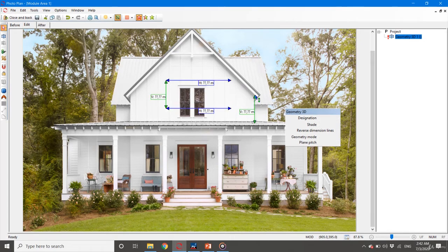Blue is the same, except for the horizontal lines with the capital letter H. Remember always to enter the correct distances or measurements so you can get accurate results and conclusions. I define the edges in the geometry I want to be a part of a plane, and I will write the length of one, and PVSol will conclude the others. If the conclusion is wrong, check the red lines' placement as the first step, and the green and blue lines too.